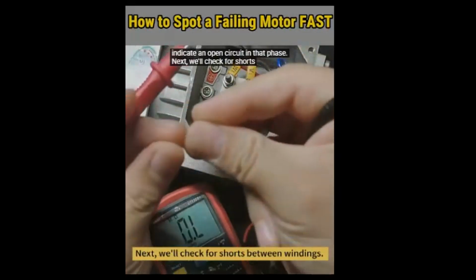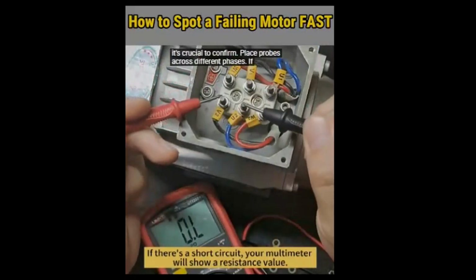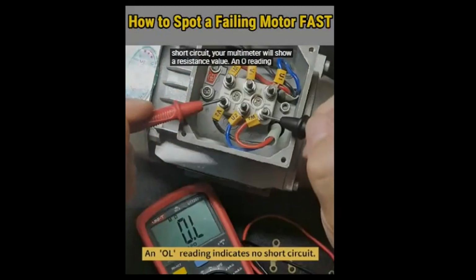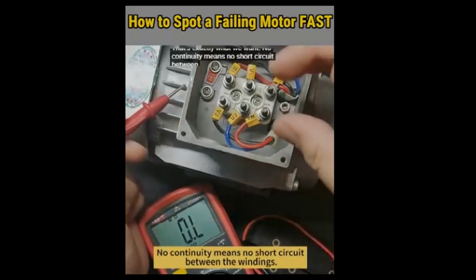Next, we'll check for shorts between windings. While windings are insulated, it's crucial to confirm. Place probes across different phases. If there's a short circuit, your multimeter will show a resistance value. An OL reading indicates no short circuit. All show OL. That's exactly what we want. No continuity means no short circuit between the windings.